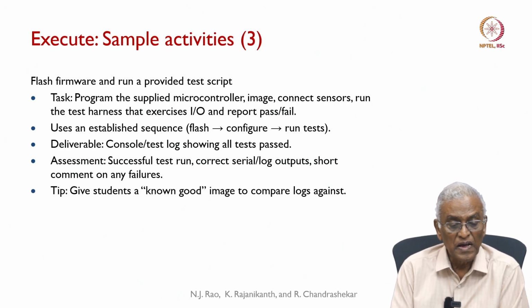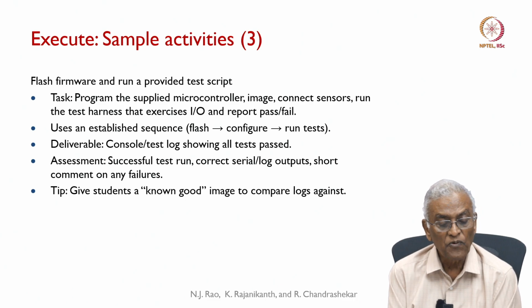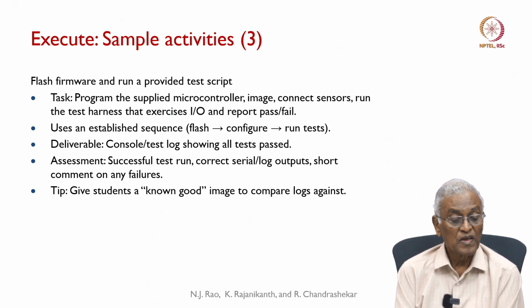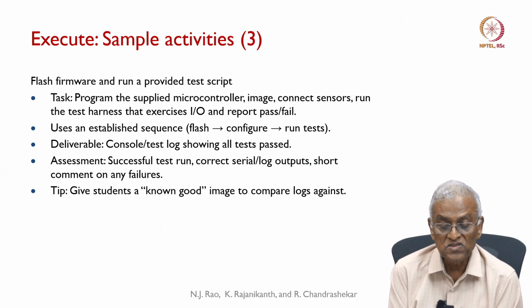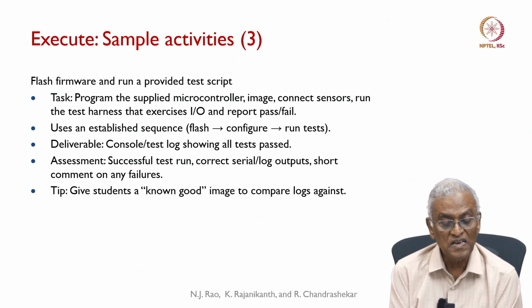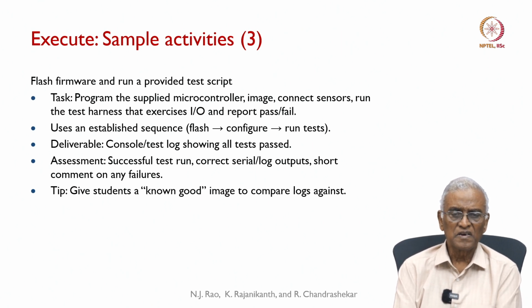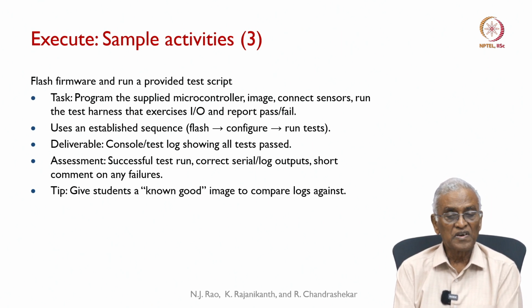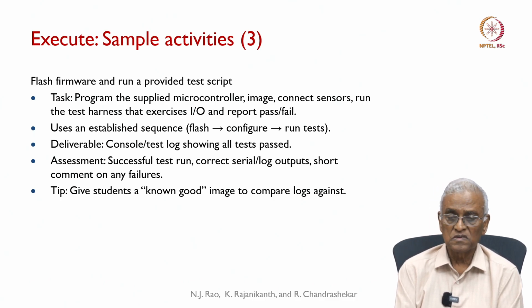Another sample activity, execute: flash firmware and run a provided test script. The task is to program the supplied microcontroller image, connect sensors, and run the test harness that exercises I/O and report pass or fail. This is something like a laboratory type of thing where you are giving an execute task. It uses an established sequence which is taught earlier: flash, configure, run tests.